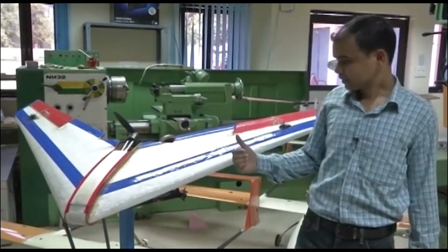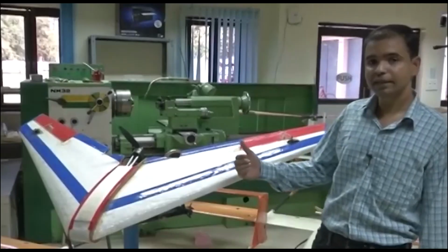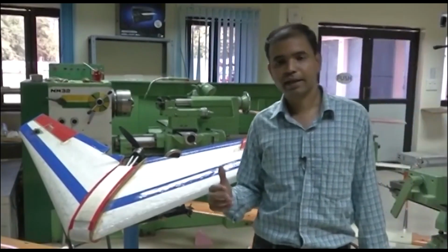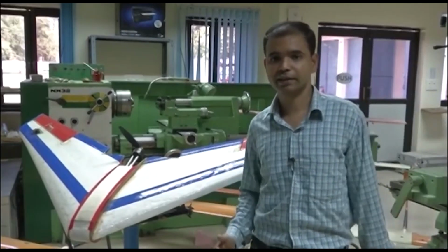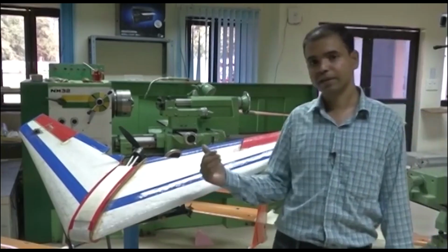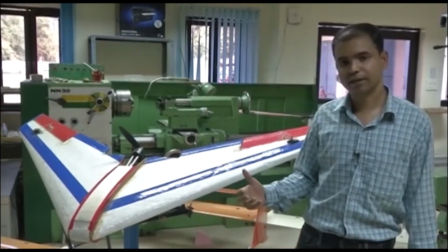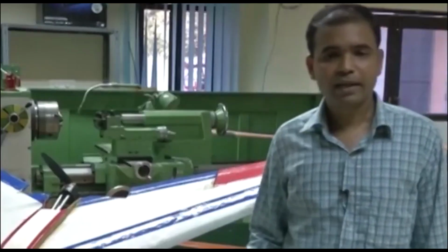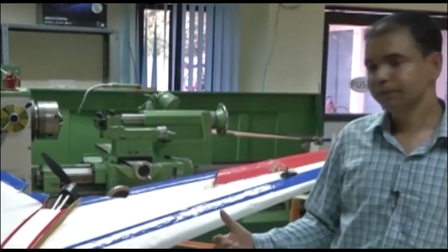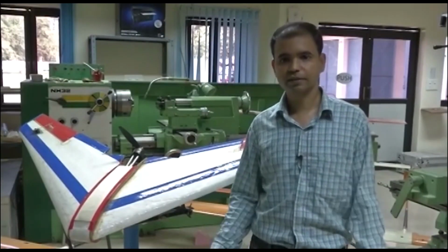You can also see we don't have any non-lift producing surface. That's why it has better aerodynamic efficiency than conventional design. We don't have any vertical surface, and vertical surface reflects the electromagnetic waves very significantly, but here we don't have any vertical surface. Therefore, its reflection of radar waves is very small, and as a result its radar cross section is very small. At the same time, if we coat it with some radar absorbent material, it becomes almost invisible to the radar, and this is the most desirable property in war applications.